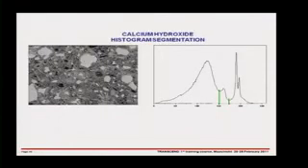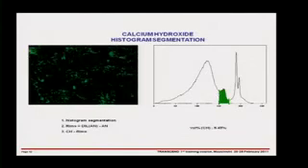Calcium hydroxide, you start to see the problems, that we've now got an overlap of this calcium hydroxide peak with the CSH peak. It makes it very difficult to discriminate the calcium hydroxide. We can pull out an image like that, which is quite good for looking at the distribution, but not very good for quantification. You generally find the amount of calcium hydroxide you measure here is much, much less than what you measure by either X-ray diffraction or by thermogravimetric analysis.